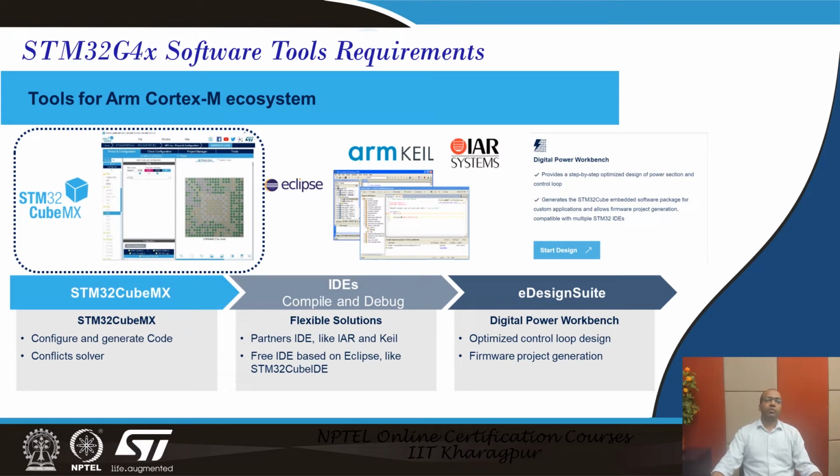The first software tool available from ST Microelectronics is STM32CubeMX. It's a graphical user interface tool. This tool is quite handy in generating the application firmware. This tool helps in the microcontroller selection, configuring various pins of the microcontroller, initialization of the peripherals, and eventually generating the first level of code for three different IDEs, that is IAR, Keil, and STM32CubeIDE. The next session will be dedicated to STM32CubeMX, where we will be focusing on the initialization of various peripherals, the MCU pin configurations, and eventually generating the code.